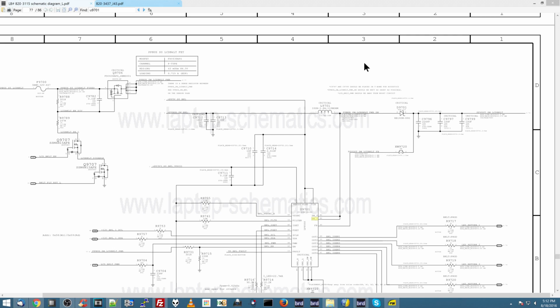Now, once the voltage is raised from that stopping short, you're going to have this diode here. Now, the idea here is that the diode is only going to let the power pass in one direction. So instead of going forward and backward, it can only go forwards. It can only go from left to right. These capacitors over here are going to be used as a battery.